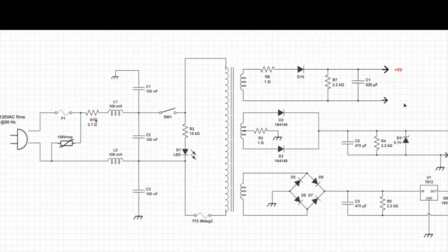It limits what we call in-rush current. Now, what is in-rush current? You've all observed it at your house. Large current devices, things like your air conditioner, central air, your microwave oven. You turn it on, and for a split second, you see your lights flicker or your lights just dim, just for a split second. That's because these devices sometimes require a bunch of current to get running. So you just see this little flicker.